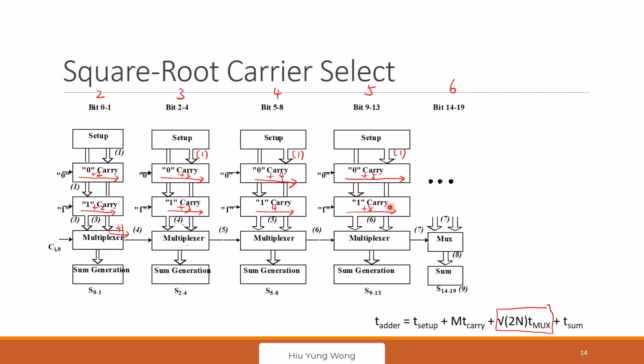And remember, try to do all the routing in the bit cell first, so that you don't need to do too many routing when you go to higher level. When you do the routing well in the first bit, then the rest you just put together and they will connect naturally. When you do the layout, your goal is that in the cell, you want to abut all the metal to the edge. So you put another cell, they will just connect automatically. You don't need to do a higher level routing. Okay, any questions?